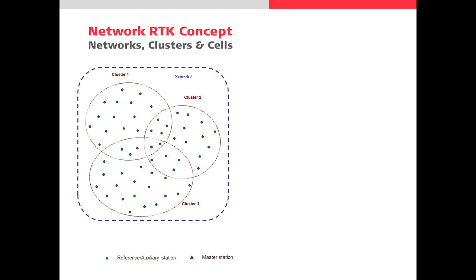Another reason can be a mixture of equipment. We could have GPS and full GNSS equipment out there, and mixing them can cause issues. So we can mix clusters so that one can be GPS because that's where we have primarily GPS equipment. One can be GNSS. Another reason, of course, is processing power.